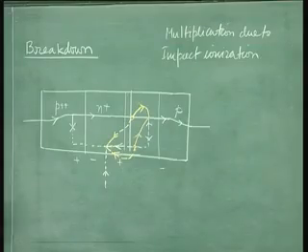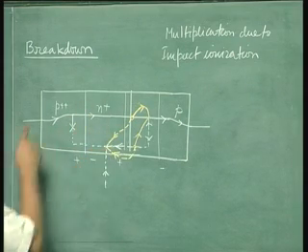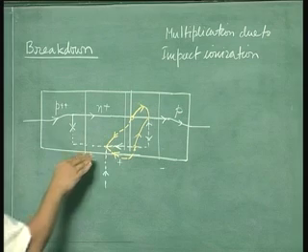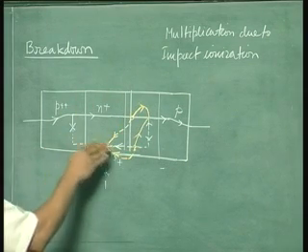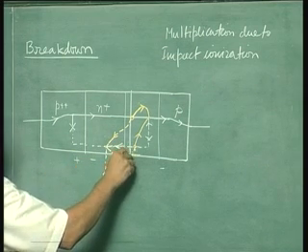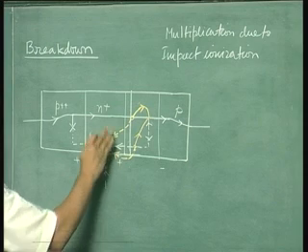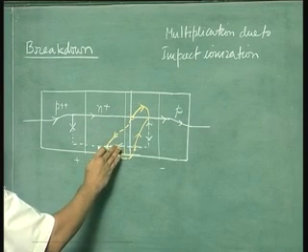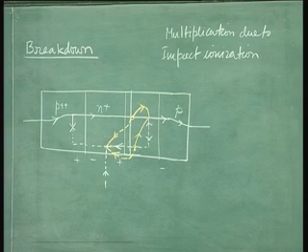So this cycle sets in, and as this cycle sets in, the current starts increasing very rapidly. So this positive feedback, which is there because of the transistor action, because of the presence of a reverse bias junction in close proximity to the forward bias junction. Okay, so that is the reason why the impact ionization is causing a rapid change in current in the transistor, and this is the reason for breakdown.